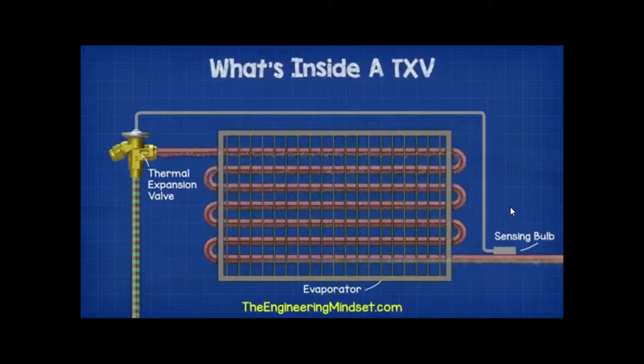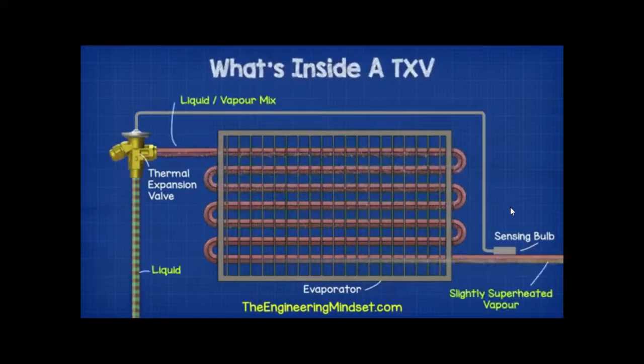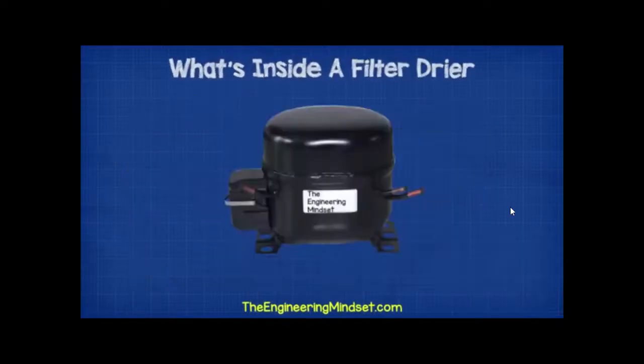This also ensures that the refrigerant is boiling off, and it will leave the evaporator as a slightly superheated vapor and prevent liquid refrigerant entering the compressor. Liquids cannot be compressed, so if they enter the compressor, this can cause severe damage and even destroy it.